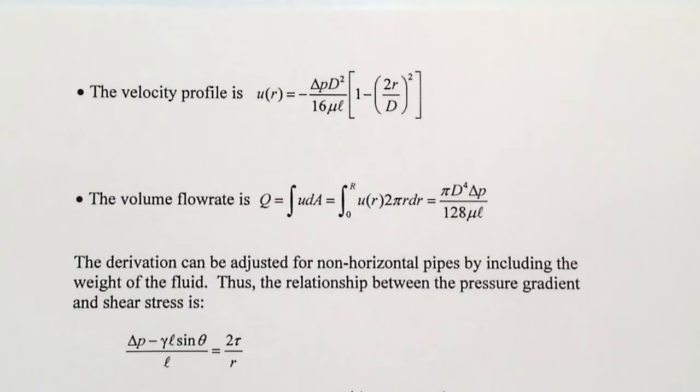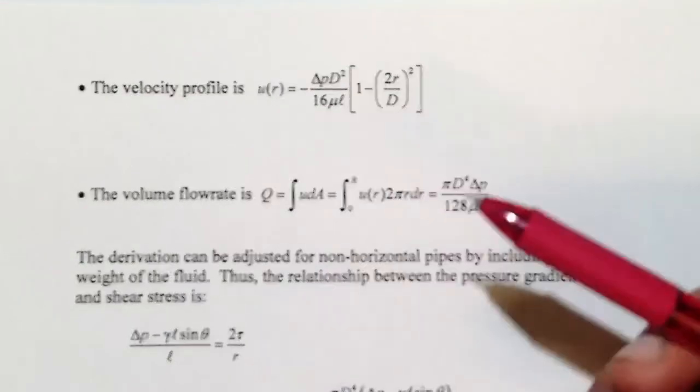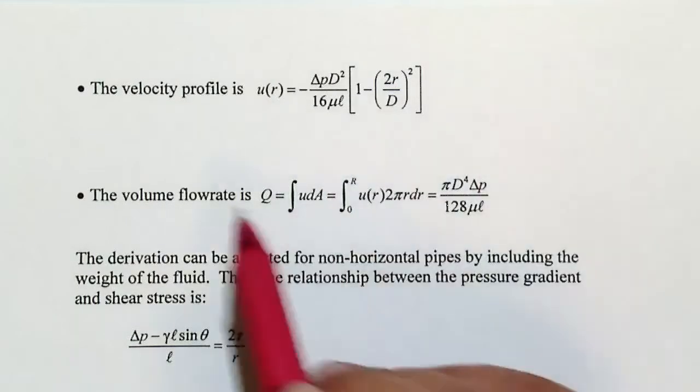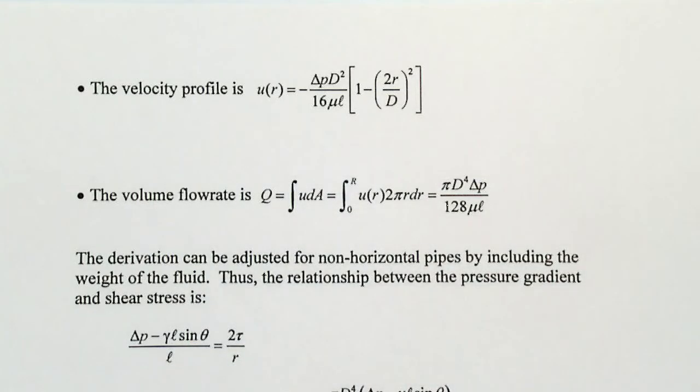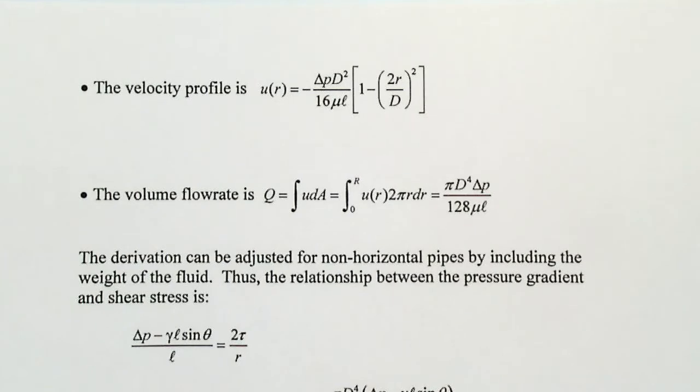By taking the integral you don't need to do that again, because whenever you have that equation, it's going to be for the whole pipe, right? It's going to be the same for the whole x, and again u is only a function of r. So you'll find out the velocity u, that component of velocity in the x direction, because the flow is only one dimensional and it's only in the x direction, but it's not a function of x. So it is moving in x because the component of velocity is in the x direction, but it's not changing with x. That's the difference. So this u is only a function of r.